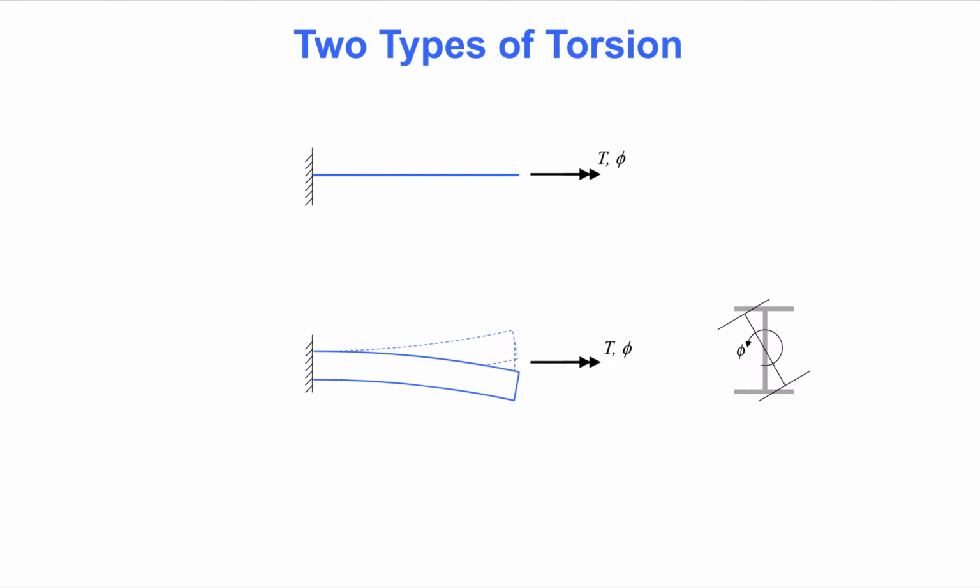St. Venant torsion is formulated in terms of shear stress. This means that St. Venant torsion lets the applied torque be carried by shear stress in the cross-section. The other torsion theory, referred to as warping torsion, includes axial stress. Although warping torsion is the subject of another video, you may here see that the bending of the flanges of this cross-section causes axial stress at the left-hand side of the beam. As a matter of fact, the theory of warping torsion has many similarities with Euler-Bernoulli beam theory, which is also formulated primarily in terms of axial stress.